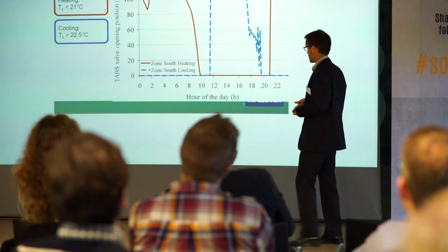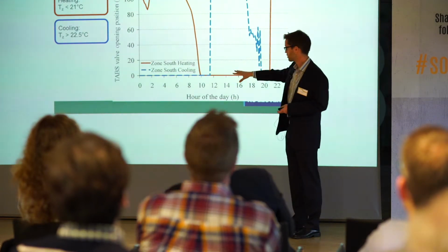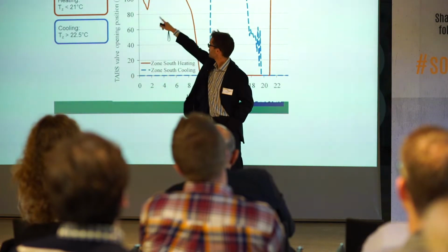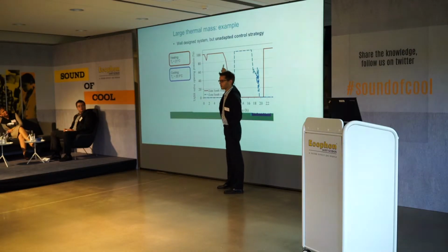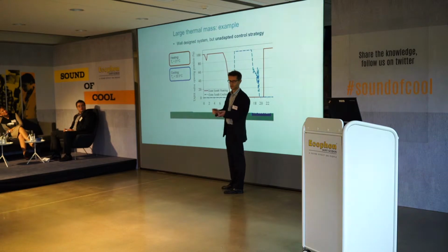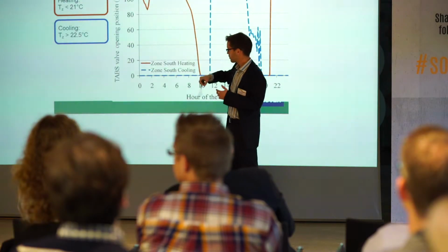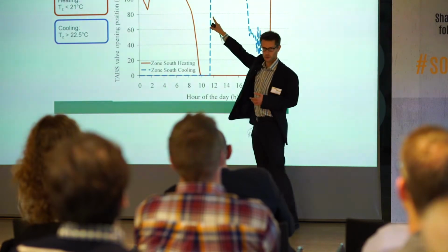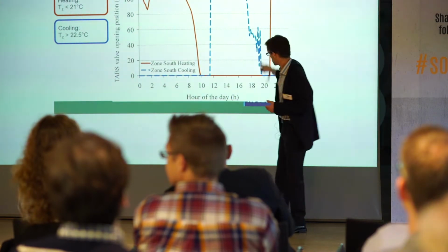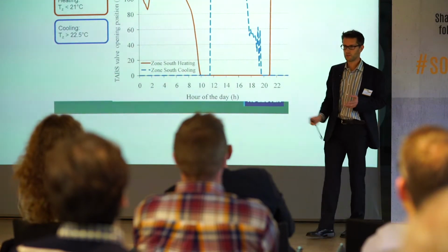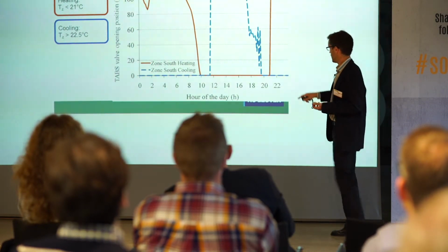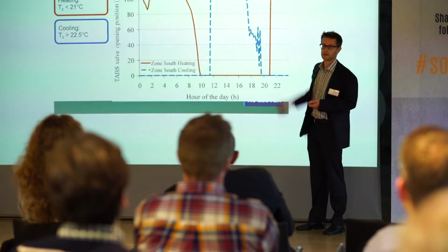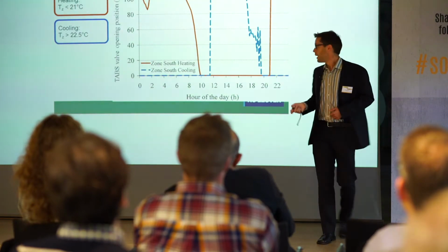So in a day, I think it was in April somewhere, this is what was happening. So during the night, the heating was on. And in the beginning of the day, people come in, put their computer on, the sun starts shining. So the temperature in the zone rises, the heating shuts down, and a few hours later, the cooling starts up. So at the end of the day, exactly the same. People go away, the sun doesn't shine anymore. So a few hours after the cooling has shut down, the heating is on again.